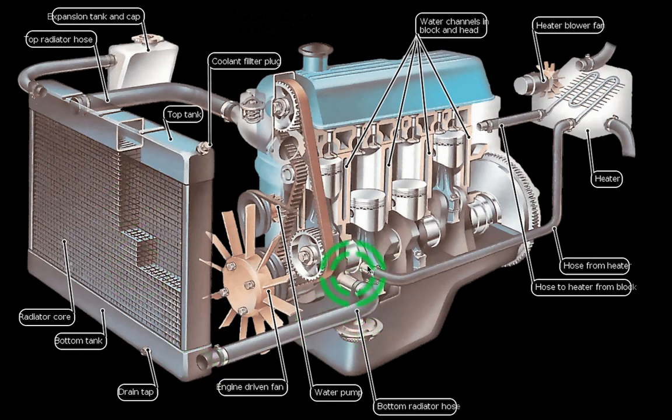Once it goes below 88, let's say 88 is supposed to open, now it's cooled, the thing has cooled it down, so it's reached 80. So this valve is slightly open, so there's a pressure. That pressure actually helps, because the water pump is pushing the water.